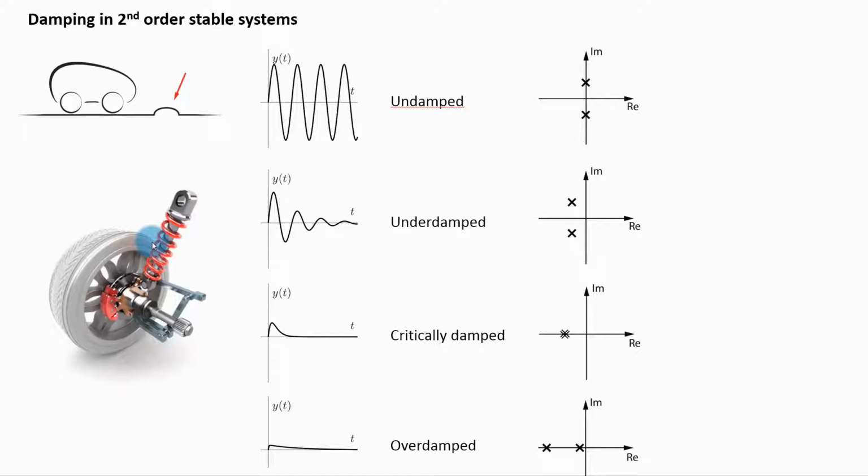But the wheel suspension is not going to work well if you only use a spring to position your wheel. Why not? Well, to explain this, I will start with the worst case scenario, and that would be the case when you have an ideal spring with no friction or energy loss in the system. If some bump compresses such a spring in an ideal frictionless case, such a spring would start to oscillate and the wheel would start to jump up and down and it would never stop doing it. This response we call undamped.